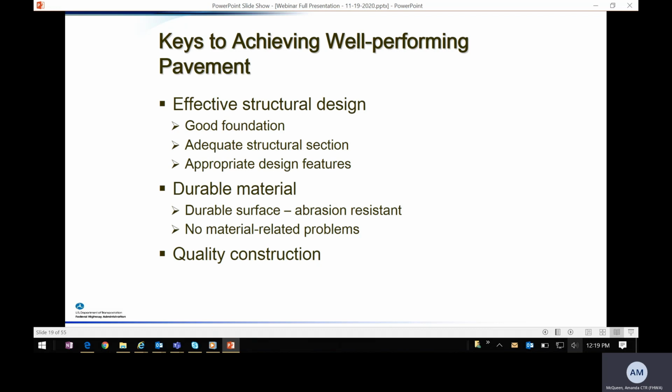I mean, at the end of the day, if you think in terms of pavement thicknesses, we're not going to change that so much by improving these models. We'll still probably most likely have the similar ranges of thickness for concrete pavements. For highways that might be anywhere from 8 to 12 inches. And we might have similar ranges for asphalt pavements. But one of the reasons that we tend to overlook foundation is that we design pavements based on pavement response.